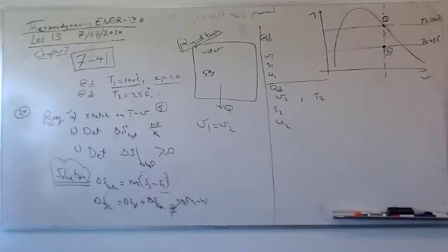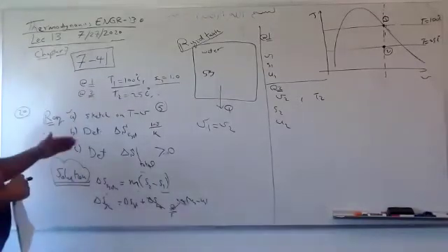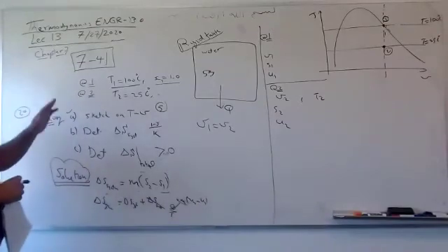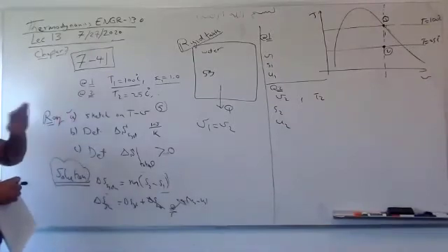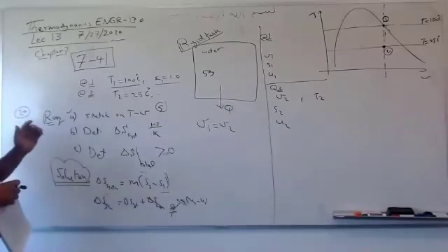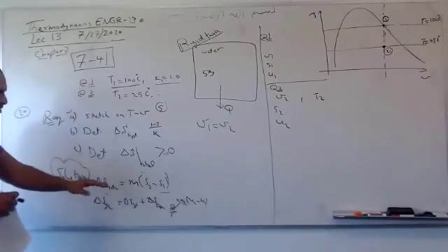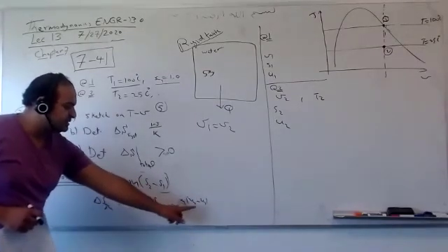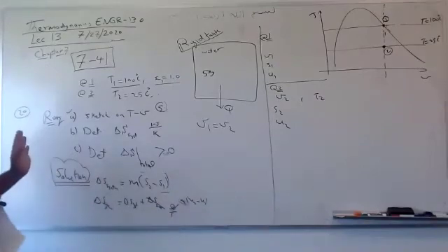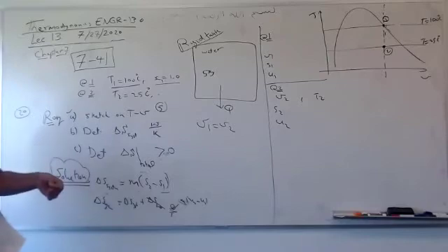Some people, which I don't like, for state 1, say, I have 6 variables, I get everything. I will give you P1, H1, U1, V1, S1, everything, which is a waste of time. You need to know what properties you need. So write a kind of dummy equation for what you want. I want this, so it needs this, it needs that. I don't need H's. I need pressure, unless it's needed. So you need to know what you want before you solve, to save time when you use the table.